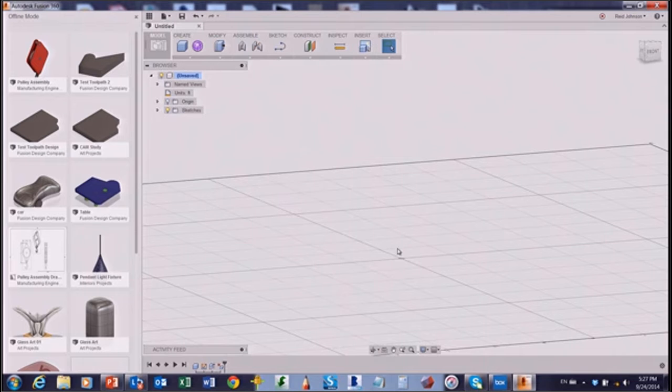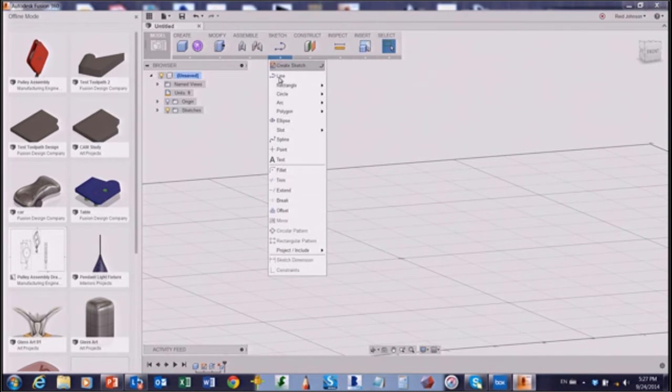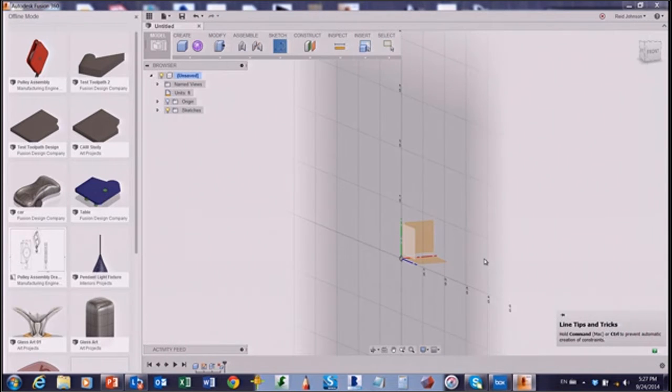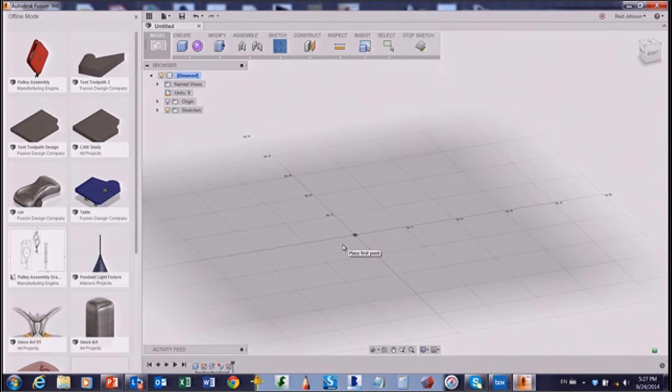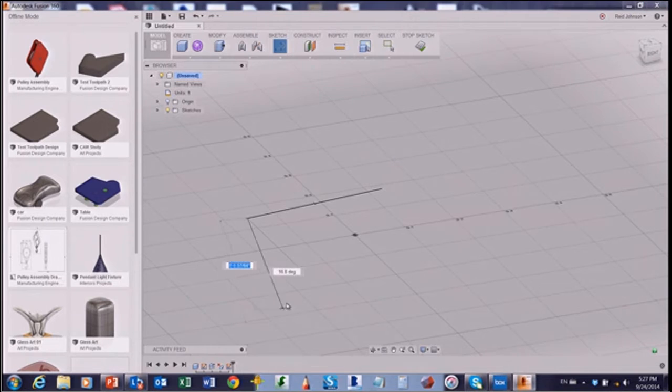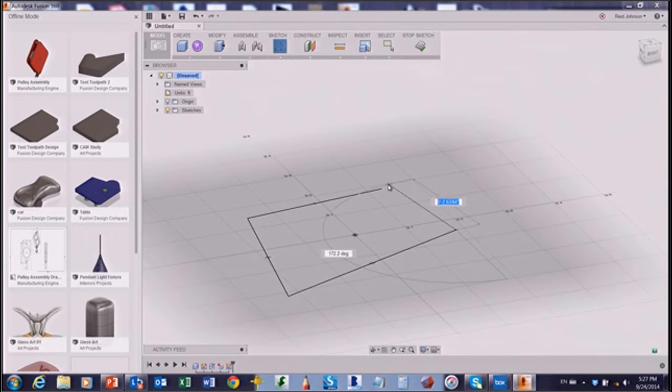We'll do it a little bit differently. If you guys start with the Line tool, you can sketch out. Just click on Sketch. You'll see under all of these, it's deceivingly simple, the toolbar. But if you pull these down, there's actually lots of options for each of these. We'll just do a basic line. It always asks you which plane to draw on. So when you start, I recommend clicking on the ground plane, and then you can click and draw away. When you get back to the start, it'll give you a little blue box to let you know that you've closed the loop. It turns yellow to let you know it's closed.